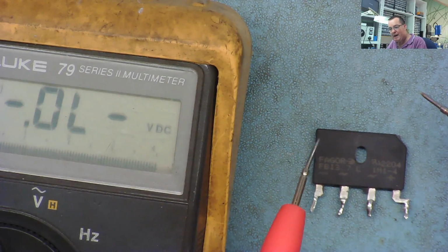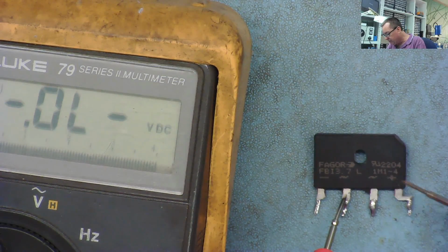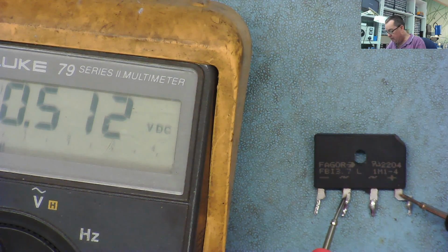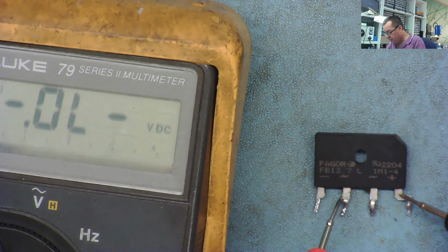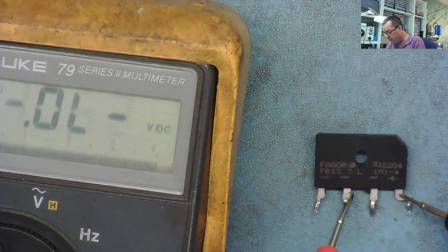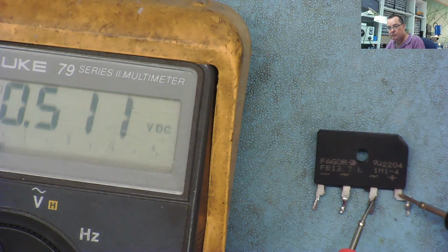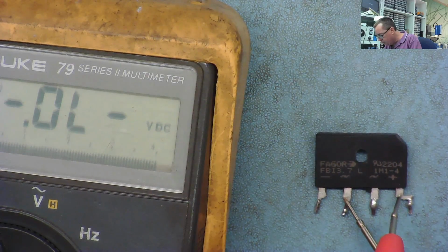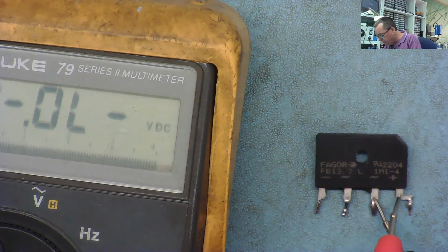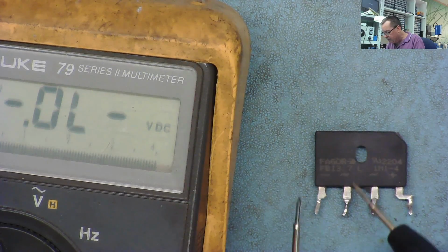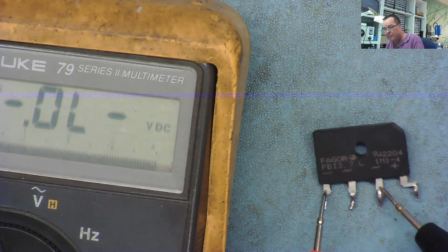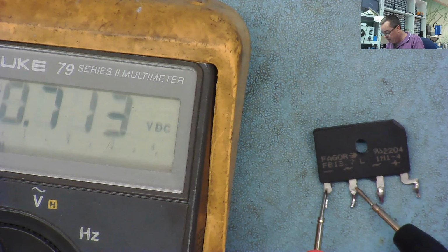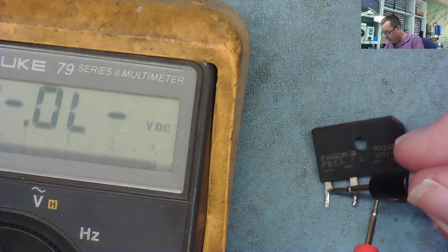We start with the red lead on one of the AC terminals, and it should conduct to the positive. And we can see the voltage drop, yeah? And the other AC terminal should also conduct. So both of those, when positive, should conduct to the positive terminal. But if we put the black one on here, it shouldn't conduct. Nothing. Okay? Now let's go the other way. So this is your negative terminal. With the negative, you put the black lead to either of these, and it conducts. It's the opposite way around, yeah? And in this case, if you put the red lead to here, it doesn't conduct.